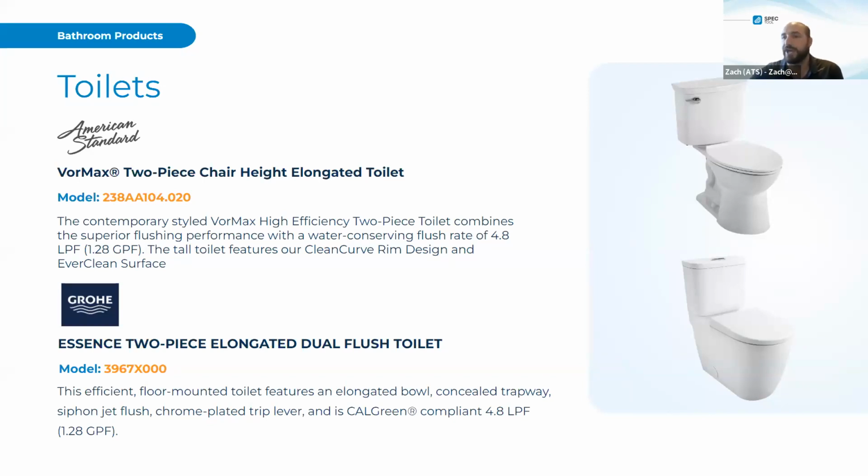With that, there's been some changes to the products to make sure that they are efficiently meeting the commercial standards for flushing, making sure they have over a 600 gram MAP test rating. And most of the toilets from American Standard or the Lixil family of companies, including Grohe and DXV, are going to be up towards that 800, 1000 gram MAP test rating.